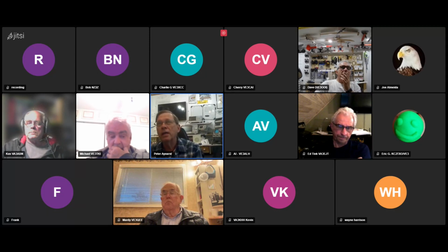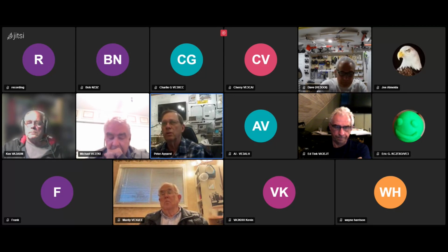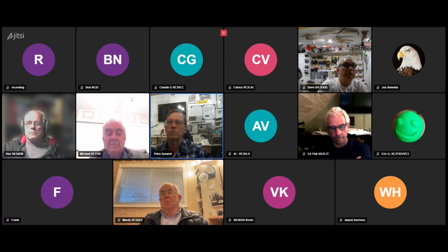And not only that, it's more accurate. As I mentioned earlier on, placing your cursors is not necessarily an accurate way. You may not be able to put it on the exact spot that you need to put it on. Whereas, when you're putting these measure statements in there, it's calculating the actual peaks and valleys, whatever it is that you're asking it to do.